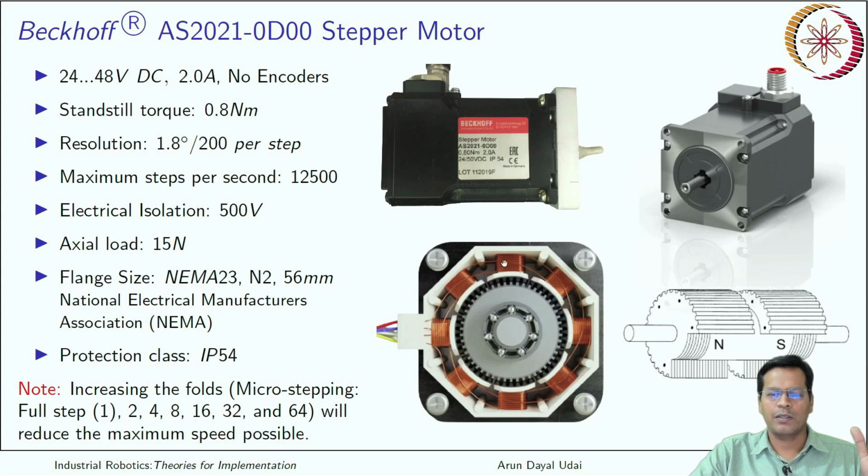So yes, it can move at very small angles. That is the reason it is able to move at 1.8 degree. But it doesn't matter, even this motor follows the principle of a bipolar stepper motor. It has 4 wires, and in the same way you have to shift your poles. So nothing to worry about, the same drivers are suitable for this as well.